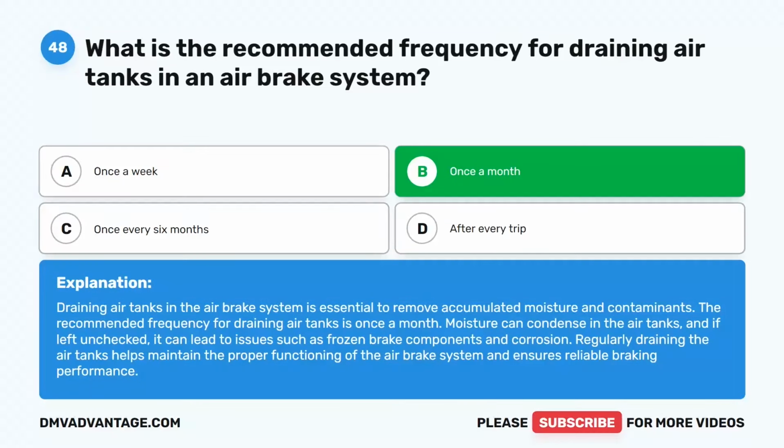The recommended frequency for draining air tanks is once a month. Moisture can condense in the air tanks, and if left unchecked, it can lead to issues such as frozen brake components and corrosion. Regularly draining the air tanks helps maintain the proper functioning of the air brake system and ensures reliable braking performance.